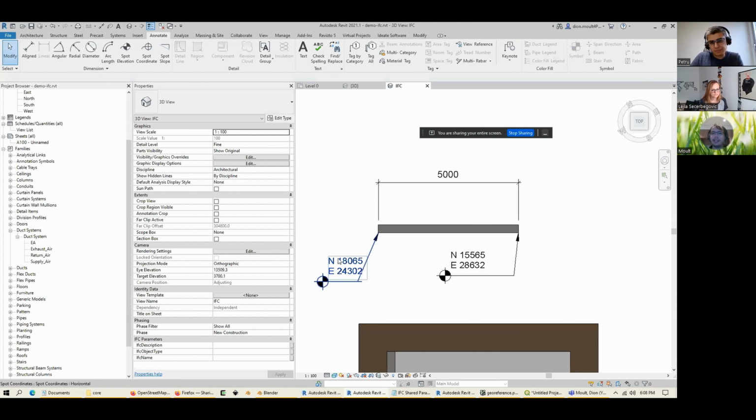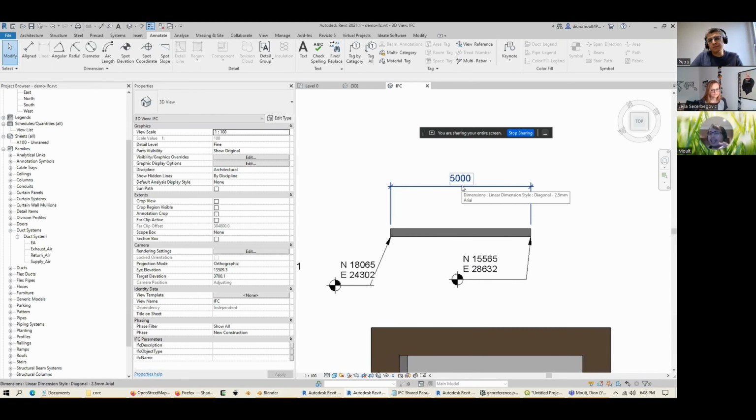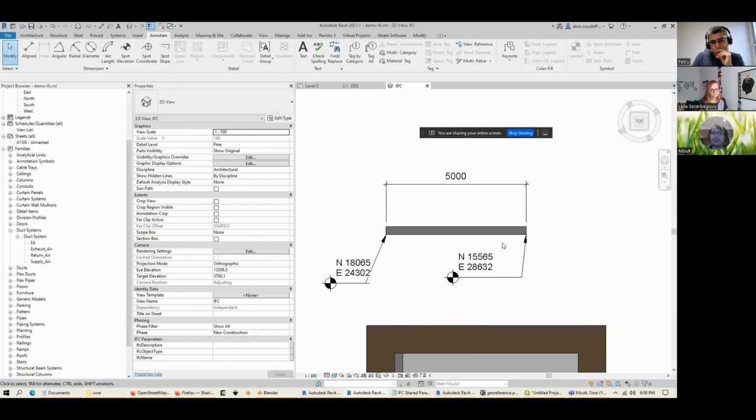You can see that this plus that equals this. That's actually incorrect. There is actually a scale factor to be applied. They're meant to be slightly different. So the third thing you have to ask your surveyor is, what is the combined scale factor for my site?